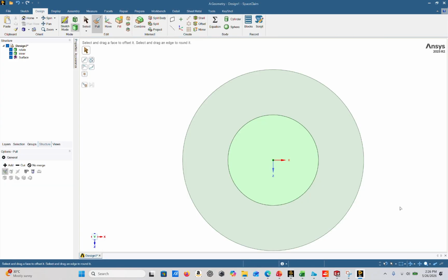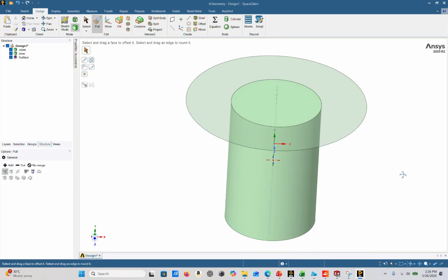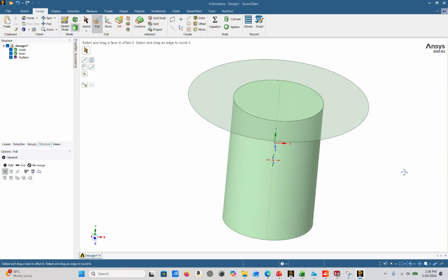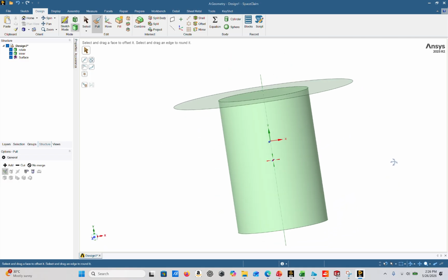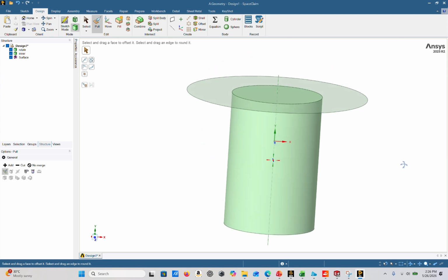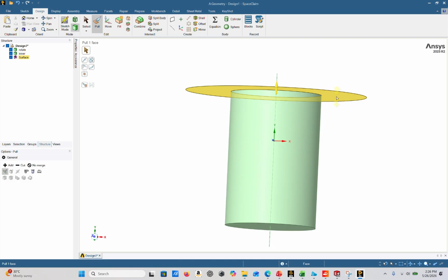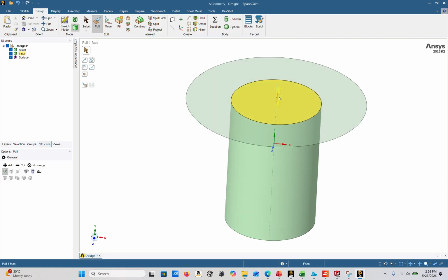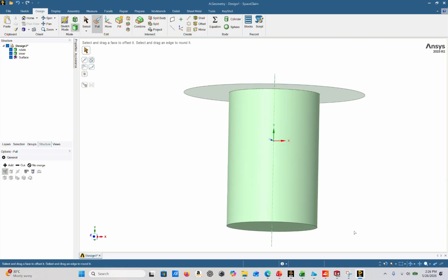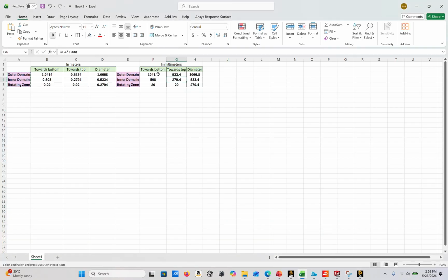and then end sketch. And what I've done here, which is not correct, is the fact that the sketch started from the surface. So we need to make sure that the surface sketch always has to start from the origin. So let's make sure that basically our surface goes to the origin.